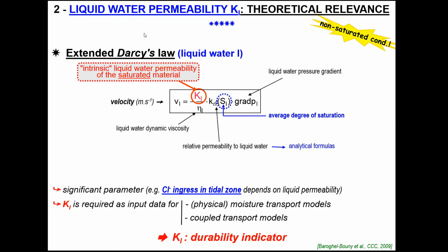But in field conditions, we usually are in non-saturated conditions. And in this case, if you remember my first line, you need to combine the process you consider, for example chloride ingress or carbonation or any other process, with moisture transport.